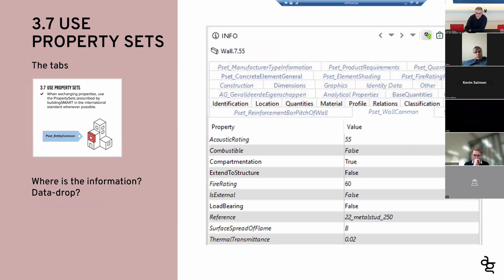So what you see here is the export where we have set the Revit property sets to be exported. And you all know Revit, so you know that constraints, phasing, identity data, graphics, dimensions, those are all parameter groups that exist in the families. And especially dimensions, you don't want those, because in order to create a window frame that's 3 meters wide and 2.5 meters high, with mullions in the middle with different dimensions, you need like 50 or 60 different dimensions to set the whole window frame to your wishes.